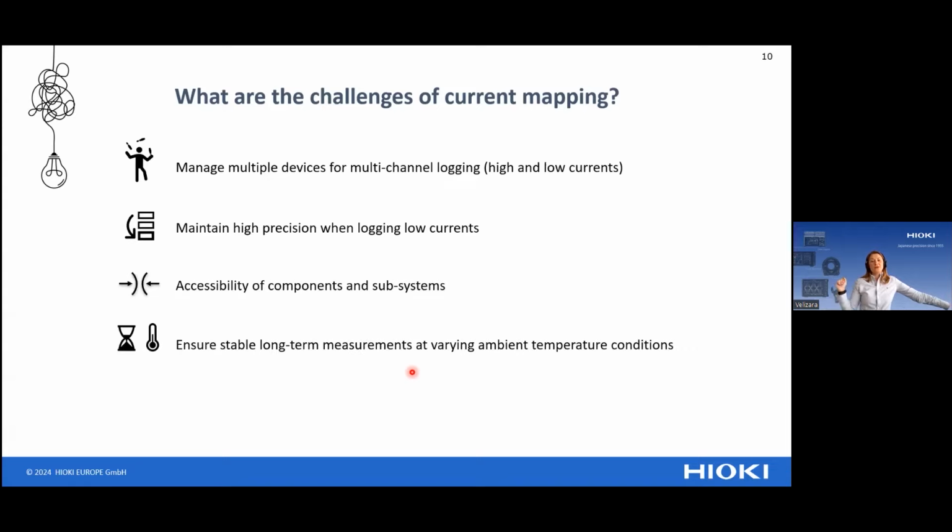And if you have measurement equipment, I will try to explain it shortly. The first thing that you have to be careful about is that you're not going to do a test over 5 minutes, obviously. So it's going to be a test that will run for longer time periods. So you need to make sure that your equipment does not drift. So you need a stable measurement over longer time periods without the need to stop the measurement in order to do adjustments, calibrations, or similar.